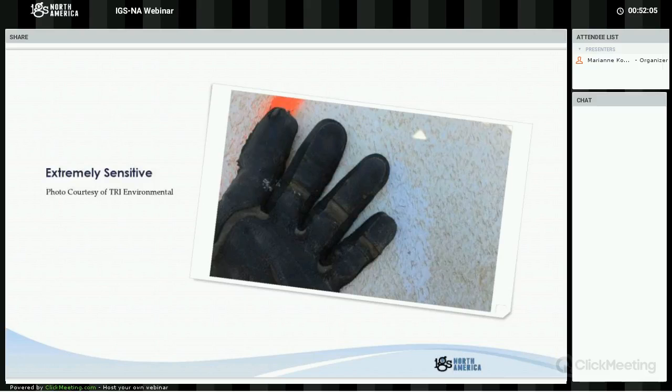Second thing, a continuously insulating layer on the top of the geomembrane. And these two layers do not come into contact with each other unless there's a leak. So what this does is it prevents the false positive on the overlaps, and it also enables all of the other leak location methods that we're talking about today.